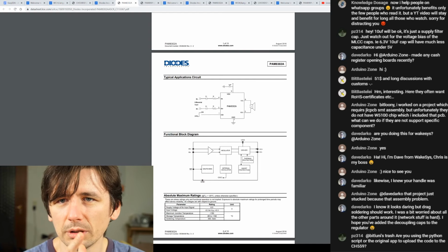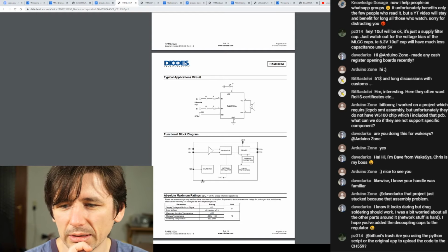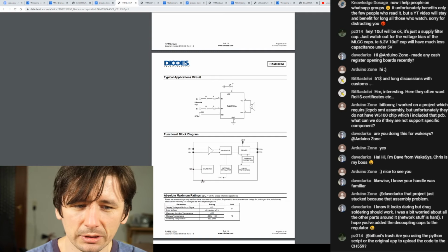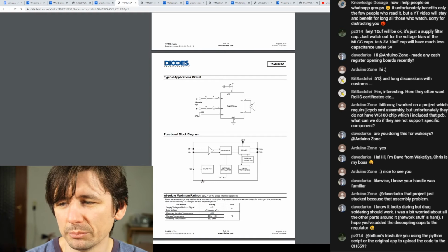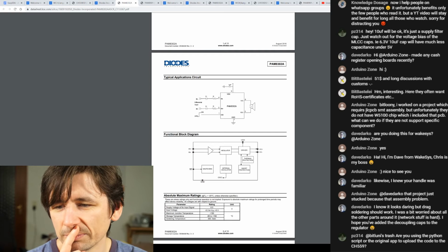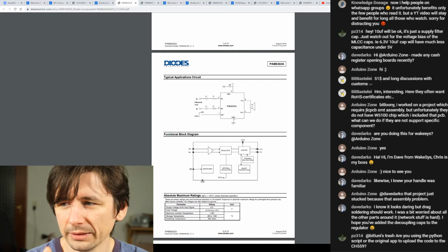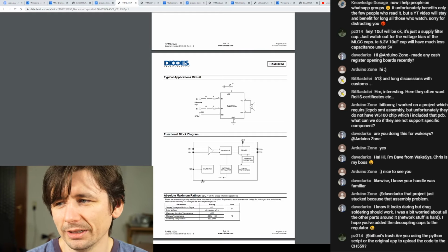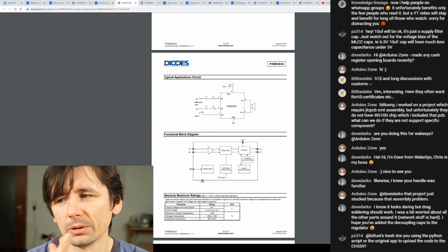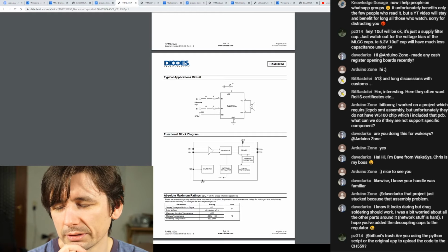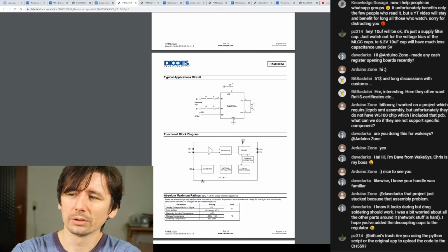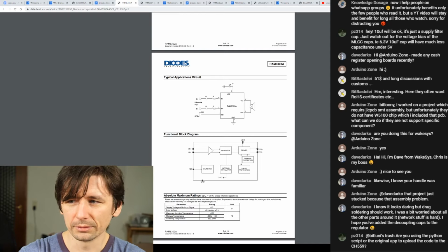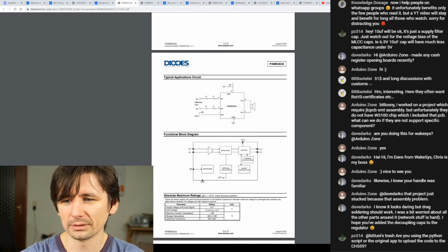I took a look at the bootloader of the CH559, and it supports also programming over a UART. I've been using the alternate UART port so far, but in my new boards I will switch to the first UART port, and then I will be able to program the CH559 from the ESP32 or any other serial port. So that will be working, hopefully. I didn't test it yet, but I saw it is possible, and you can use it even to do over the air updates of products later.